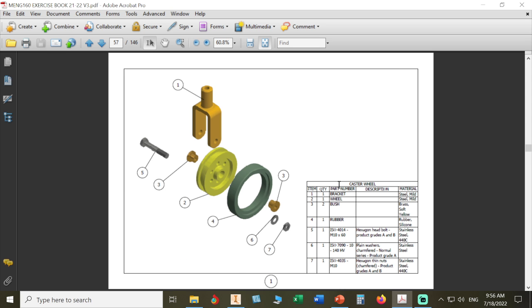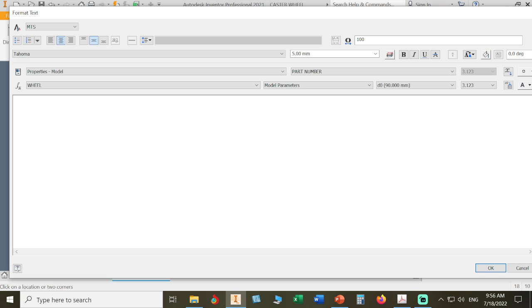You have a part number and the name of our parts under this column. So we'll go to Inventor here. This is the part number. How to insert it in our text box? Click the arrow here, add text parameter. We can, of course, now change its properties, center it, make it bold, underlined, and hit enter.